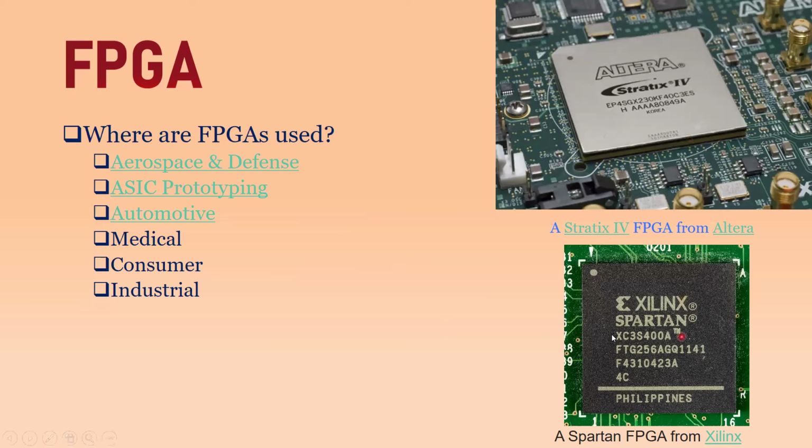So you have these blank FPGA ICs. You can actually implement that ASIC logic into the FPGA first. This is called FPGA prototyping. It is quite rapid, fast, and you can verify the functionality of the ASIC in the FPGA first. And then once you are satisfied, you can send it for the volume manufacturing of those ASIC ICs.